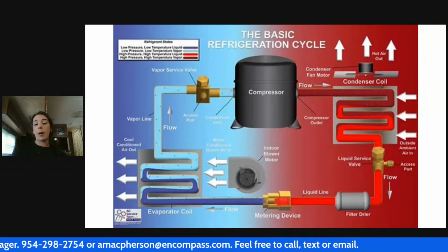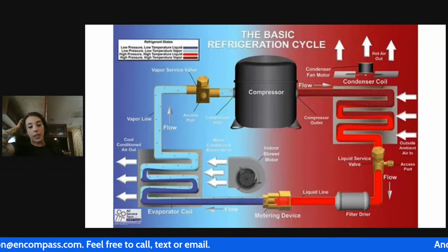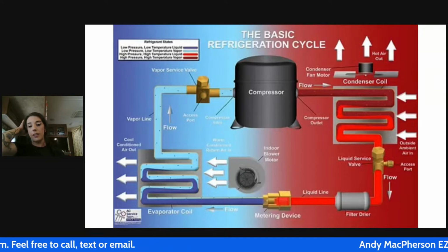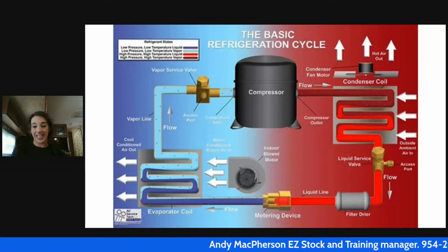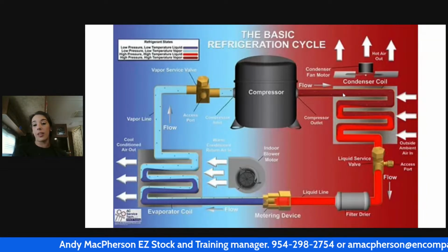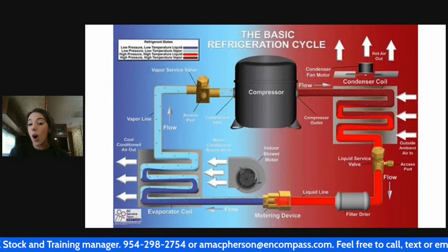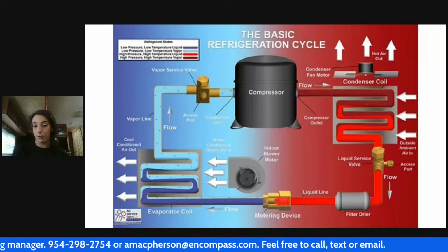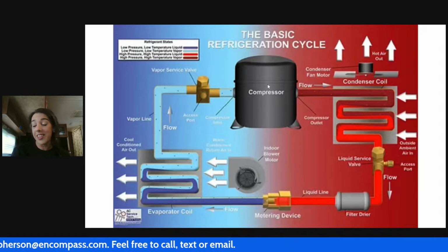Now, what if I walked up on that exact same unit and I looked at that low evaporator temperature and I said, my evaporator's empty, which means my system's low. And then I just put some more refrigerant in it. Well, at that point, my condenser is already full of liquid refrigerant. It's already holding as much as it can hold. So what's going to happen is it's going to fill with more liquid refrigerant. That only has one place to go, which is directly to the compressor.